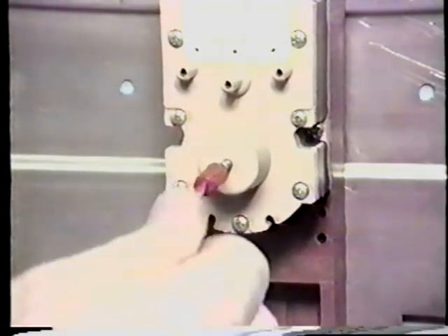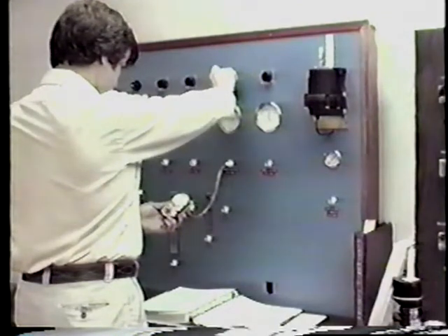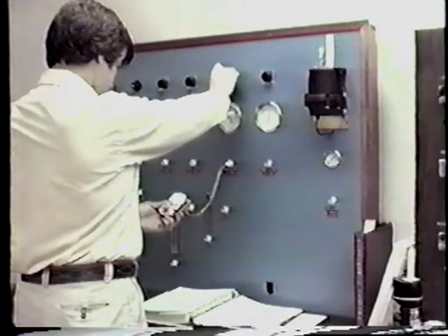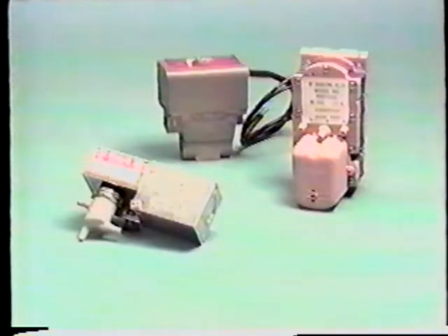The differential band is fixed at 4 PSIG and can be adjusted between 4 to 8 PSIG and 18 to 22 PSIG respectively. This adjustment should be made on a test bench where an adjustable air supply is available to ensure accurate changeover settings. The next device that will be discussed is the EP, or electric to pneumatic relays.